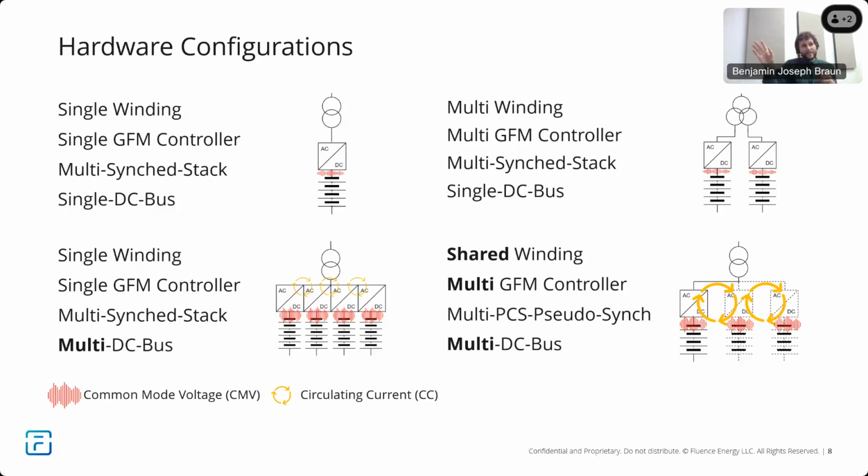Moving to the top right, effectively the same thing, but using a 3-winding transformer. You just have to take care that you spec it properly so you don't have too much coupling on those two low voltage windings there.